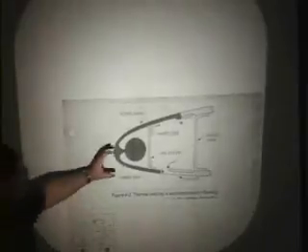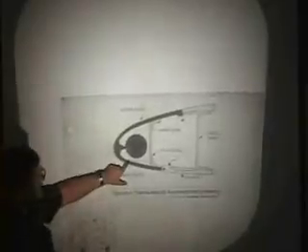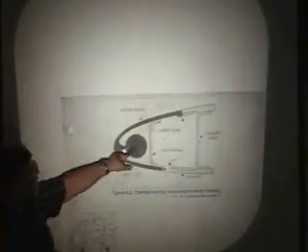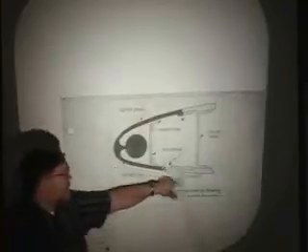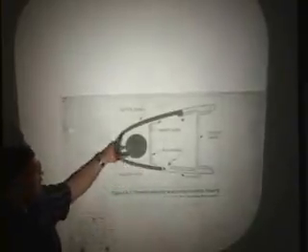And here's what it looks like. Here's a cross section. There's just a hot air duct running down the leading edge of the wing, and there's a skin on the inside about 1/2 of an inch or so, and this hot air is held between the outside skin and the inside skin. It ends up going overboard, and this air is nice and hot. And so any ice that tries to stick will melt immediately, so it won't stick at all. This is a very, very good system.